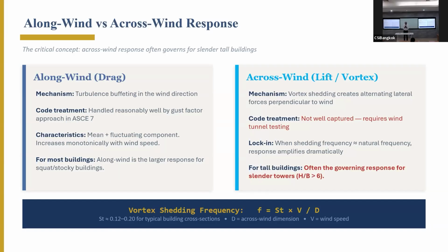So it's like this: if the wind is flowing like this and the building is moving in that direction. You would expect that if the wind is going this way, the building should move like this, but no, it moves more in that direction. That is the reason, and wind tunnel tests are able to detect that. Small changes in the building form can prevent the vortex shedding, just adding some spoilers, some openings. There's a famous saying by one wind design engineer that you have to confuse the wind.